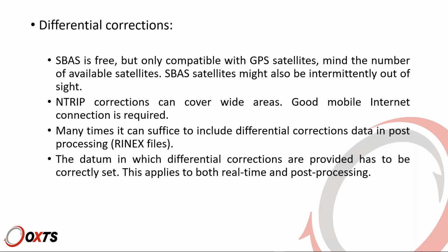So if you already have few satellites, it might not be a good idea to cut that number even more by enabling SBAS. The good news is that if you have SBAS enabled in real time, you can disable SBAS in post-processing and have your GLONASS or Beidou satellites back. So it might be worth trying to have it and see if the result is better. SBAS gives you a position accuracy of around 40-50 centimeters.